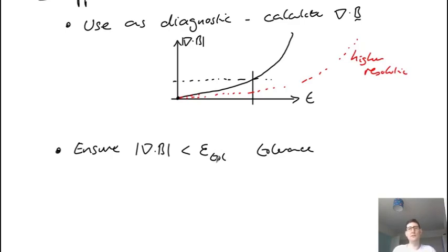In divergence cleaning, for example, there's a cleaning parameter which determines how fast the errors are removed. But if you make that very quick, it will constrain the time step and stop your simulation from running, whereas if you make it small, then the error will become larger. So there's a trade-off in how small you can make this parameter.